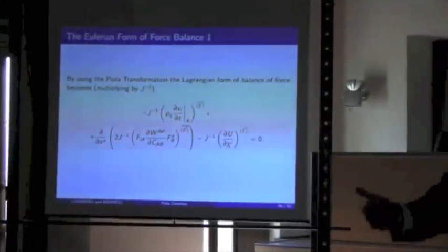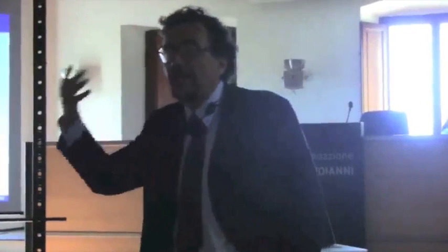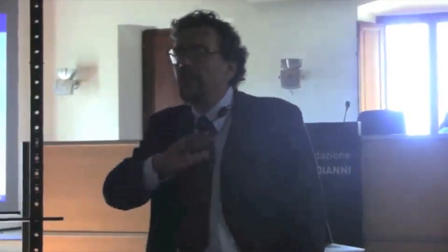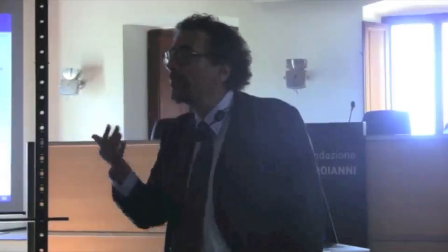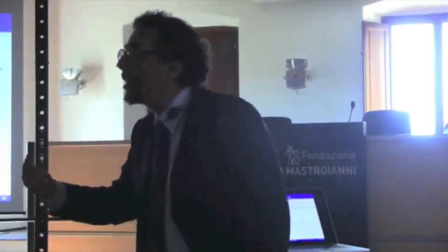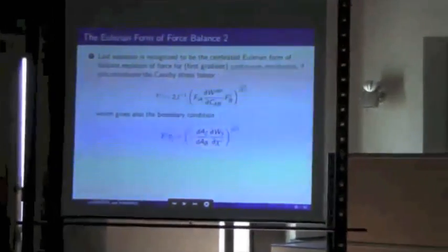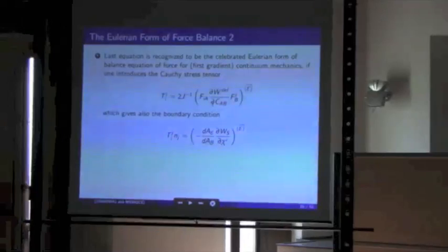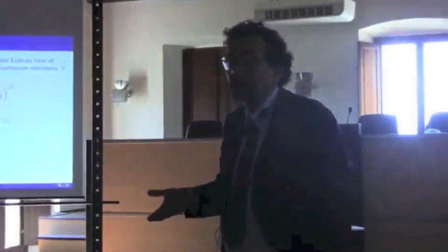Okay, then after he introduced Piola transport, and he wrote the equations written in the reference configuration, he wrote them in the Eulerian configuration. This is the only process which is left in the literature with Piola name. However, which is very important, in the literature they use it on the other side. They use it from passing from Euler to Lagrange. Why? Because they believe that so-called Cauchy stress tensor, this animal, is simpler. This is the bad luck we had because of the validity of tetrahedron argument.